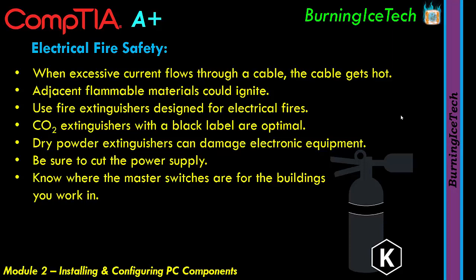So you need to have a higher gauge of cable. I think in some countries they refer to it as a higher gauge of cable. So you get yourself a thicker gauge, or just in general a thicker kind of copper cable. The thicker the cable, the higher amperage it can handle. You'll find it also normally costs you more. Quite often in some countries, if you go and buy yourself a cable, the packaging will tell you what kind of amperage it can handle. The higher the amperage, the more stuff you can load onto it.